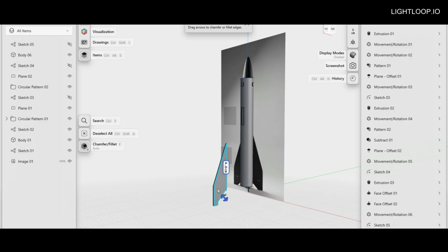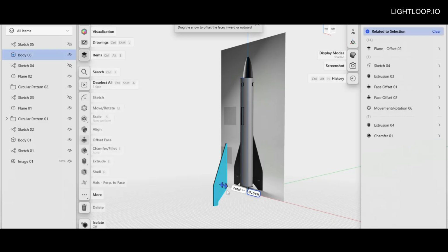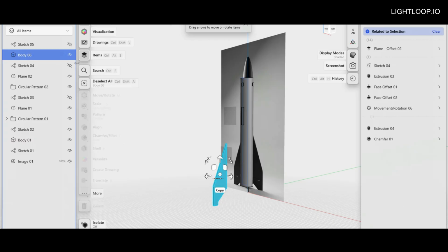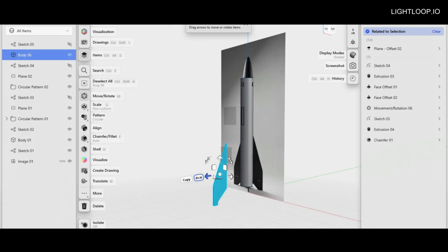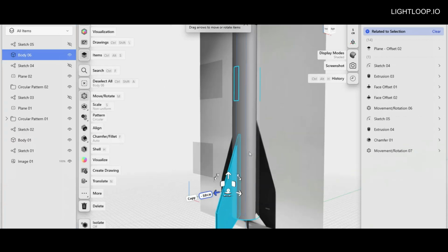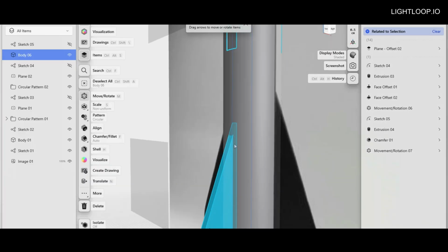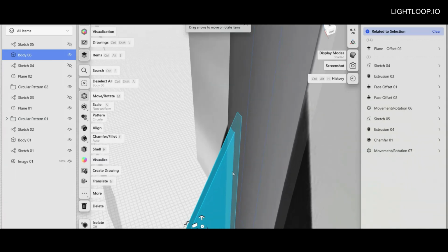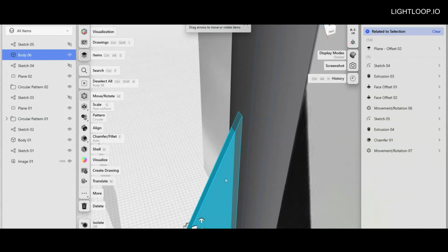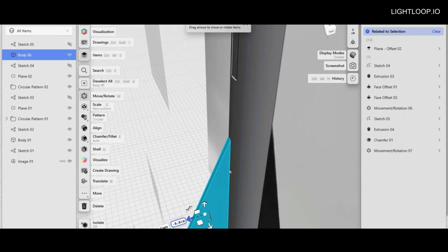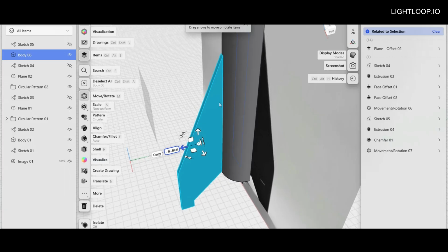So now we're going to do something a little different. Now, as you saw, the problem with the last approach was that if we pushed this new object in close to the body, it wouldn't sit flush against the surface of the rounded cylinder. Now, the way we got around that was to push the shape in just a little bit further, but this would cause some excess geometry inside the rocket body itself. But there's actually another way. Now let me pull this body out just a little bit here. And now I can position the rectangular body just close to the surface of the rocket body without touching it.